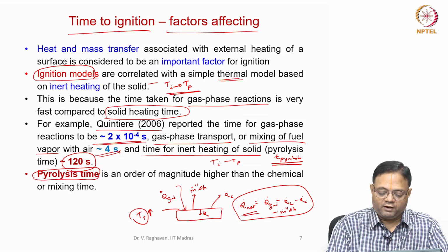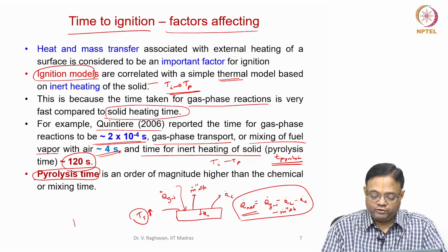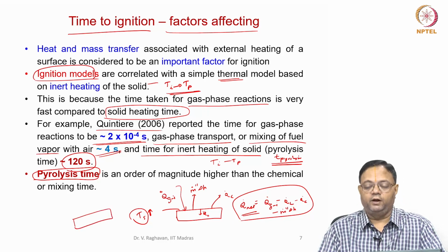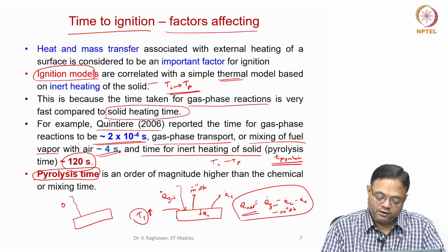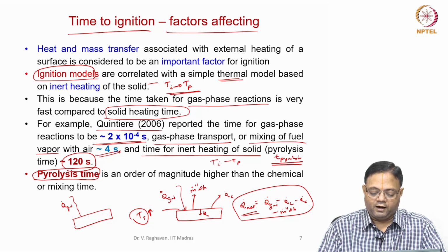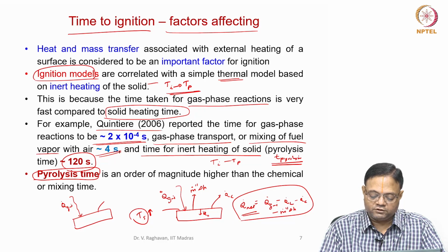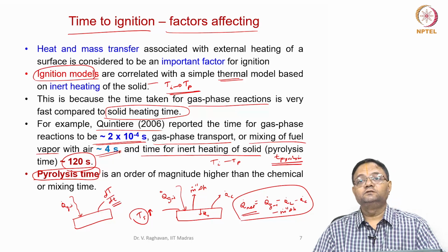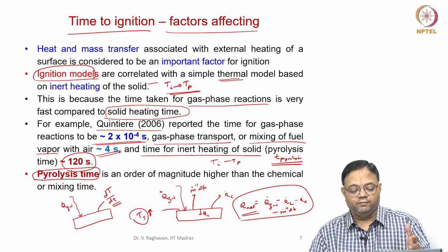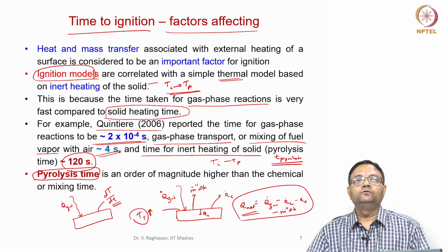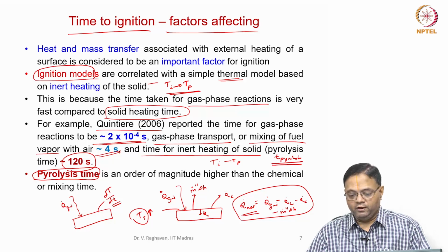So, for pyrolysis time we have to do several tests exposing the solid to different heat fluxes or heating rates and see how fast dT by dt occurs. That is very important for us. So, this will determine the time for ignition.